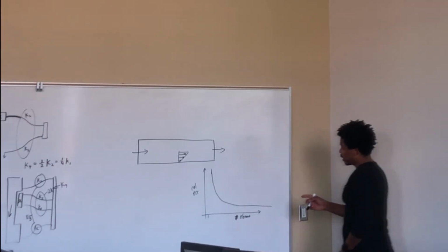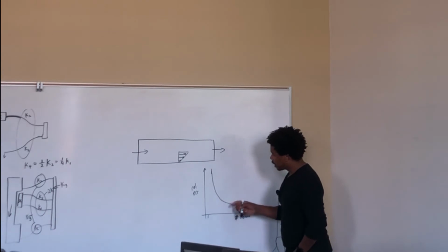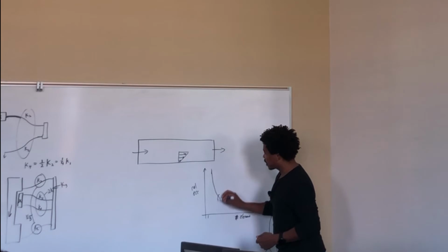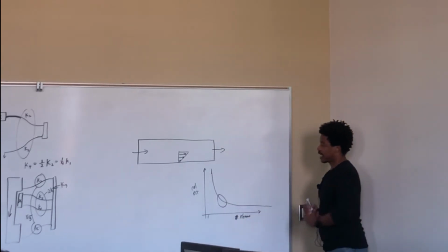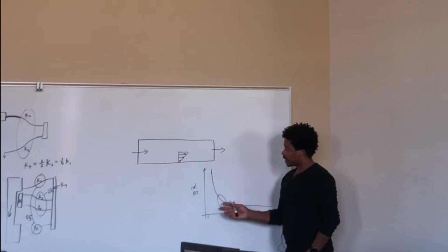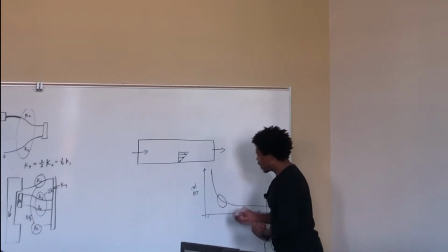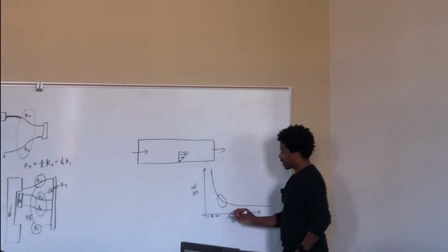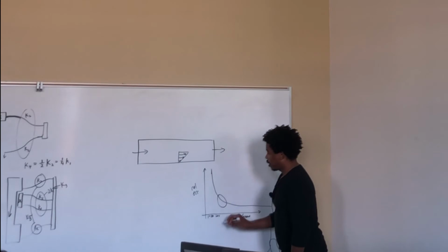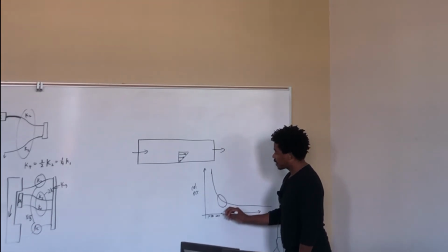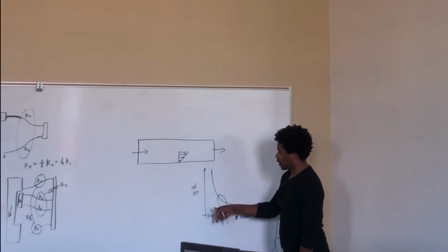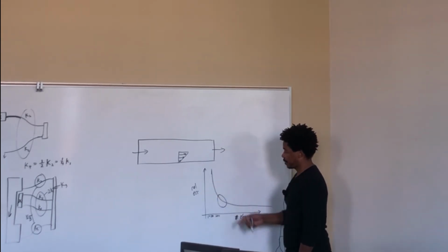But what I'm trying to explain here is that there's typically, I call this a convergence knee. It's like a little knee, right? Because if you mesh going from 1 to maybe 10 to maybe 200, well, 10 is in there somewhere. But as you increase, what happens is that you get a huge return on the relative error, where that's going down. You want your relative error to go down. You want an accurate simulation.